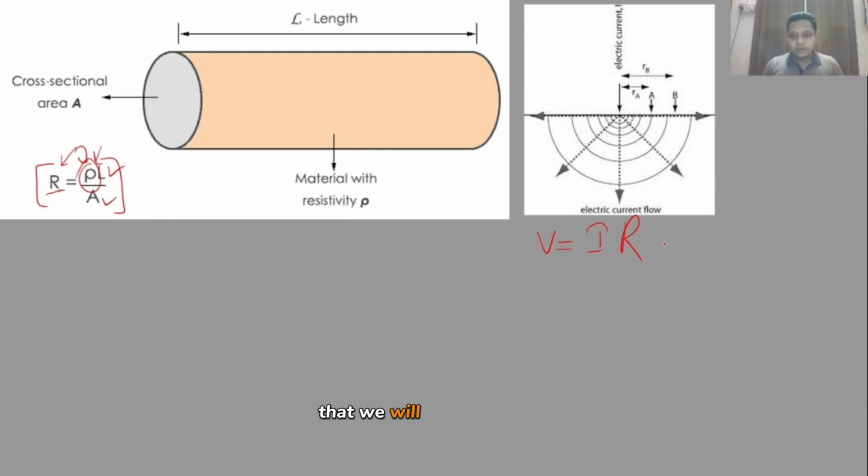Now, as I mentioned, we will use the simple Ohm's law to derive an expression of how we can calculate the voltage and indirectly the resistivity at any point on the surface of the earth. So let us assume that we put a current electrode over here on the surface. It will generate these wavefronts of spherical or hemispherical shape, we can say, because on the surface of the earth or above that in the air, current won't flow. So this will produce a hemispherical 3D wavefront, which will dissipate like this radially.